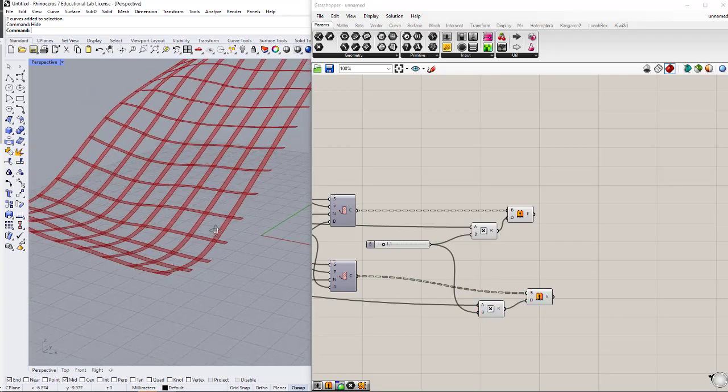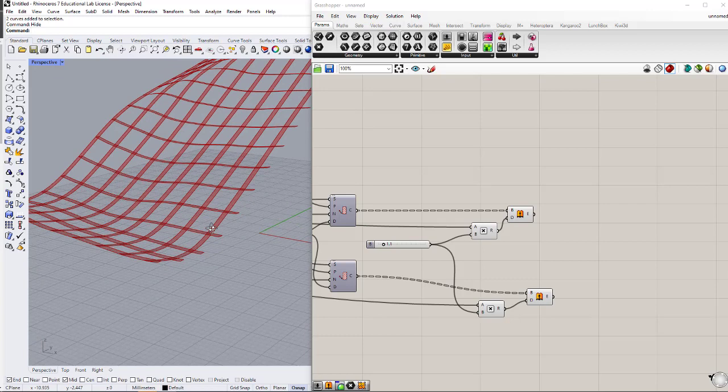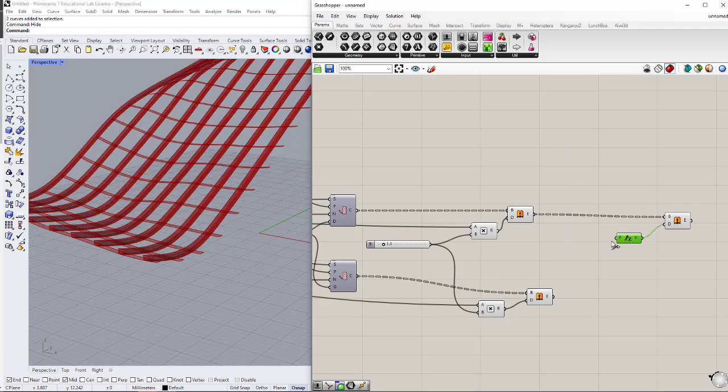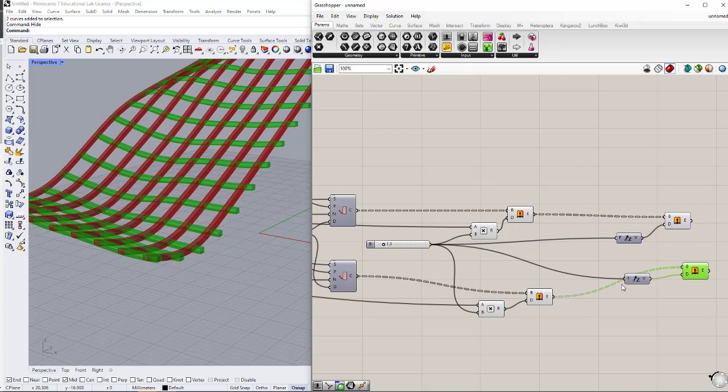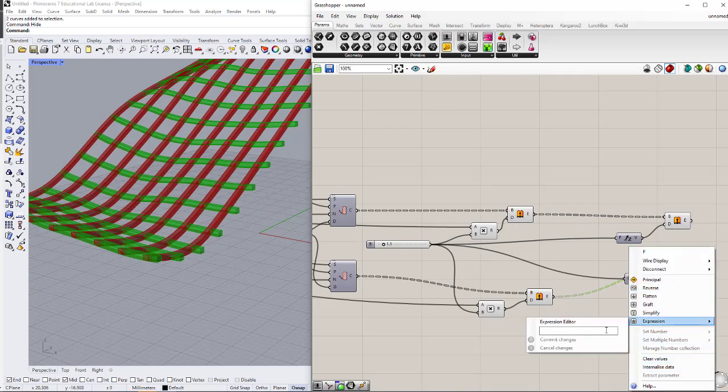But it's important to consider that I don't want these two curves to just intersect together. So I'm going to use an extrusion with Z direction of, let's say, the same number for these slabs, and for the other one, maybe I can use a negative value for the Z vector, so that they just have the opposite direction. So using -x.